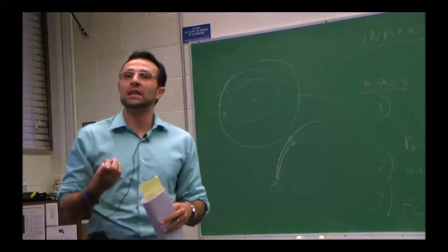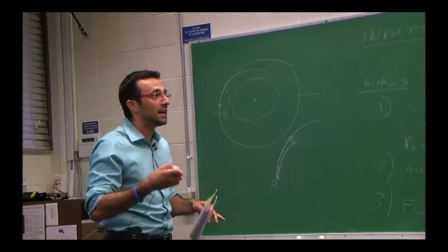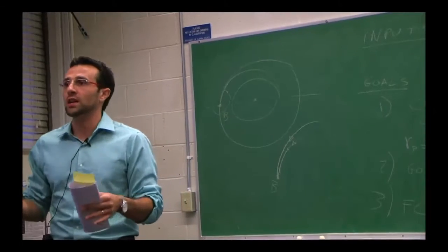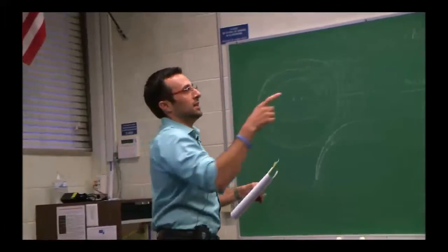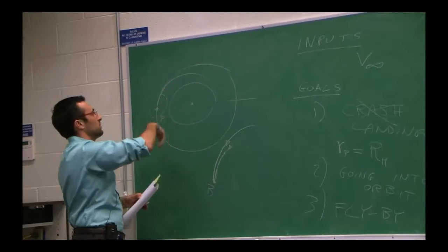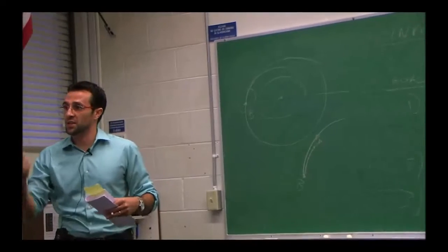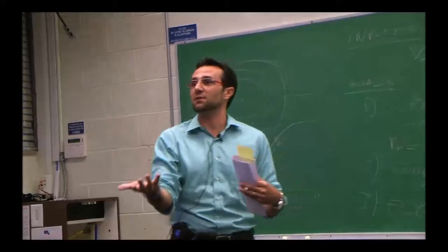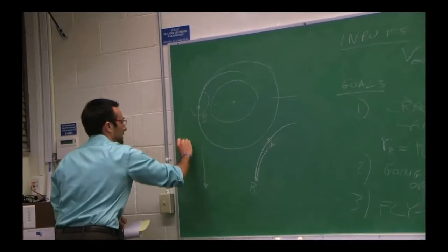We're not solving numerically and with high precision what happens in reality. Because in reality, the Sun and Mars are both affecting the trajectory of that object all the time. This is the approximation of patched conics. I decide that heliocentric trajectory goes up to the sphere of influence, then I forget about that. I just figure out a V infinity and switch to that. And since V infinity in this case happens to be pointing towards Mars, against the velocity of Mars, because of my calculation, what I did before, V of Mars will be pointing this way, right?